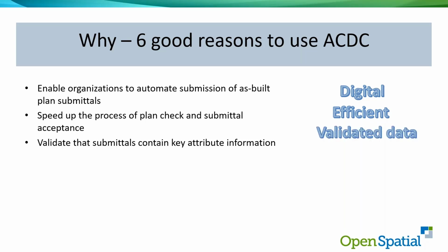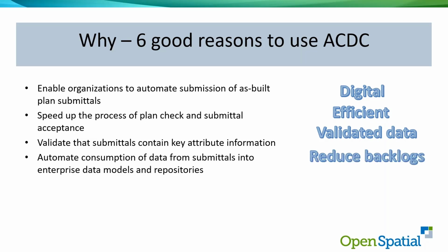The other part is we validate the data. Literally, it's about data. You want to check that you have all the depths, diameters, materials, elevations, etc. on every last piece that you want, that things are snapped, that they're closed, that they are not isolated. All of that you can do within the validation phase before you even accept the document. And that's really, really important. So that speeds things up.